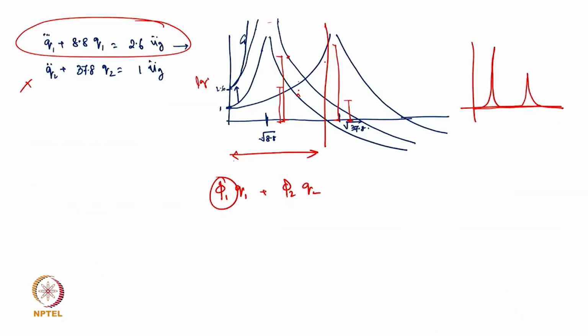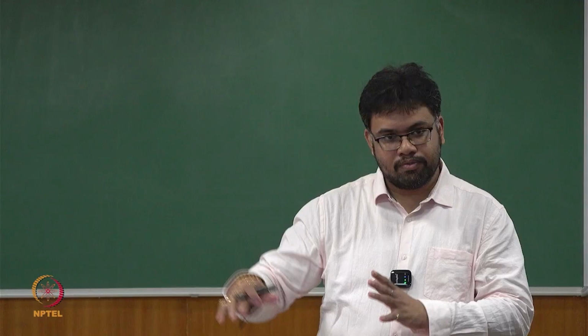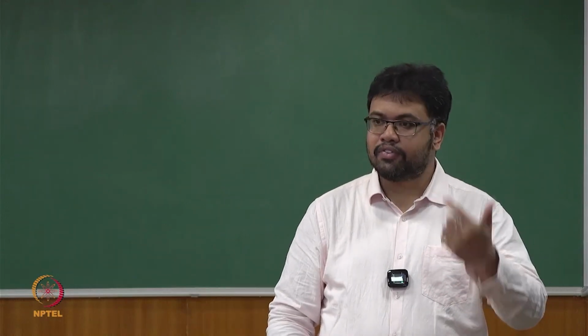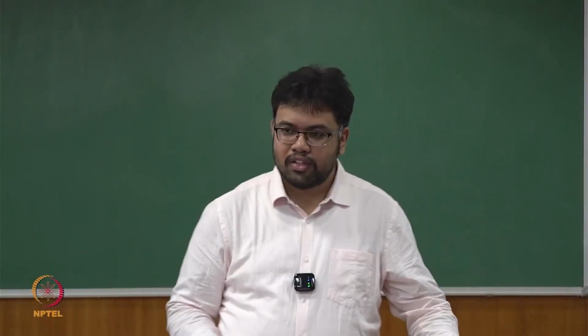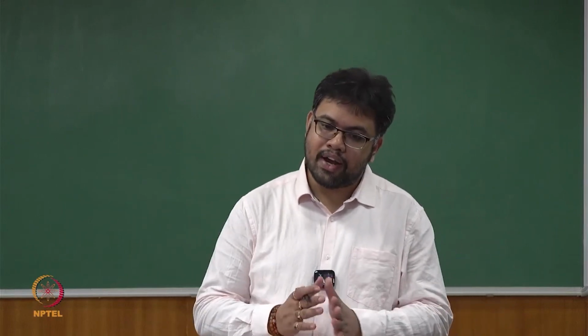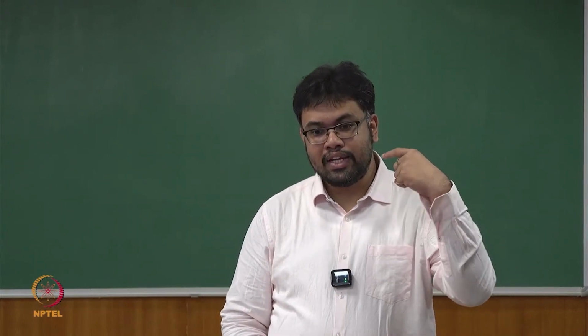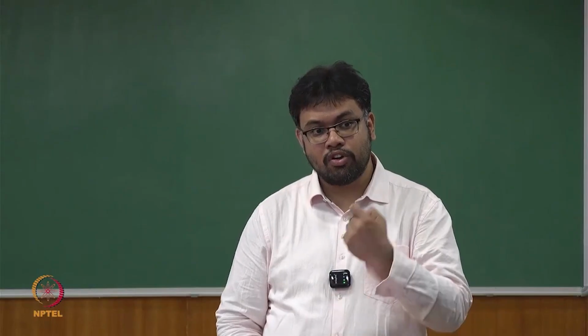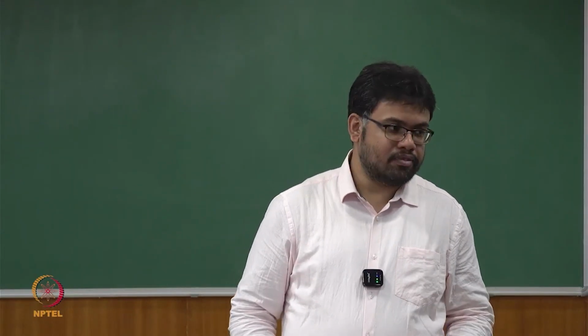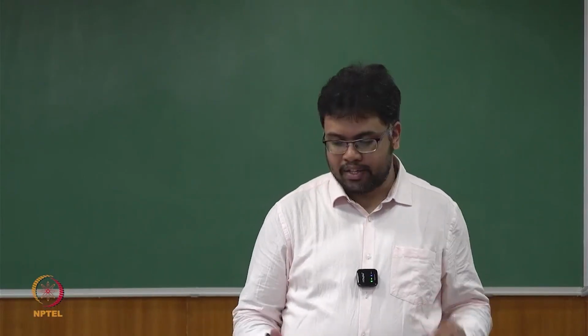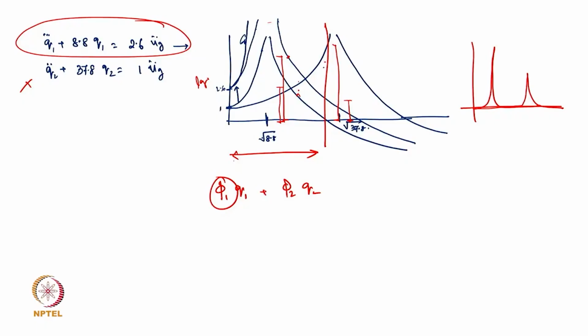So this way, more or less, we can plot both the diagrams and see where the contribution is coming from. But in general, what we can see is that if you are neglecting some modes, near the natural frequency of those modes your error could increase. Because at those points, if you see, this will try to go to infinity, so the response itself is quite high. That is actually the scenario. Any doubt up to that?